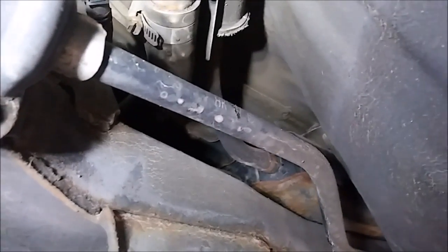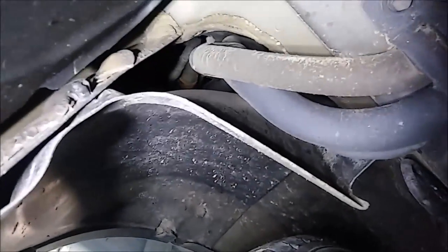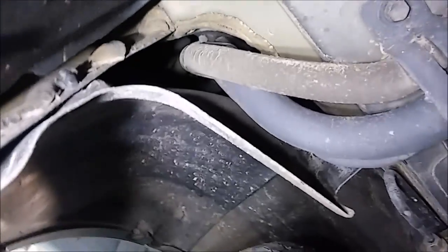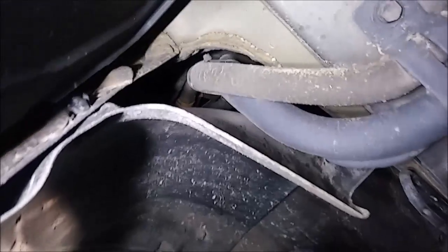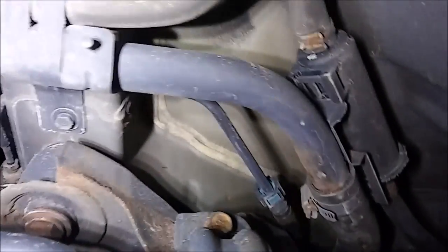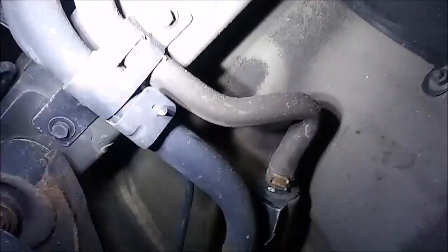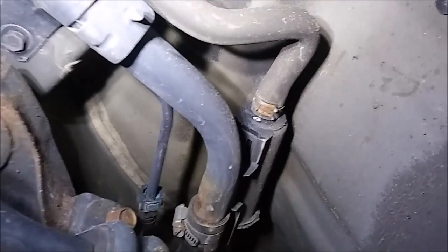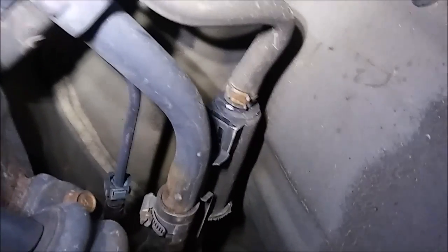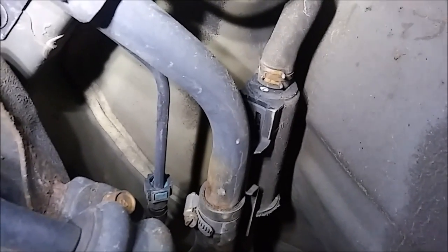seal this EVAP system, and we can do that one of two ways. What the engine computer does is it energizes the vent solenoid that lives up there, which closes the valve and seals the tank off. I'm not about to get up there, at least not yet, to manually energize this. So just for direction purposes, I'm just going to clamp this hose off here with a pair of vice grips or something like that, and we're going to mechanically seal the vent valve, seal the system, and then we can run this test manually ourselves by energizing the purge solenoid up front under the